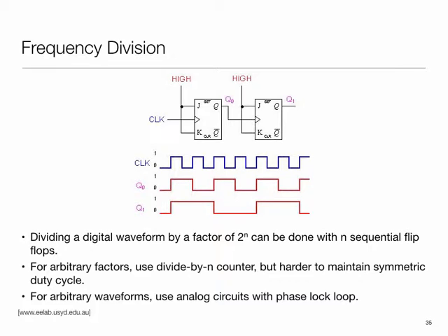So next up, after I have my clock signal, that clock signal is typically not at the right frequency. I need to generate clocks of different frequencies out of it before it can be made use of. So you have to divide the frequency, you have to multiply the frequency. Those are a couple of things. So how can I multiply the frequency? Anyone? Division is easy. Flip-flops, at least division by powers of 2 is really easy. And so how can I multiply the frequency?